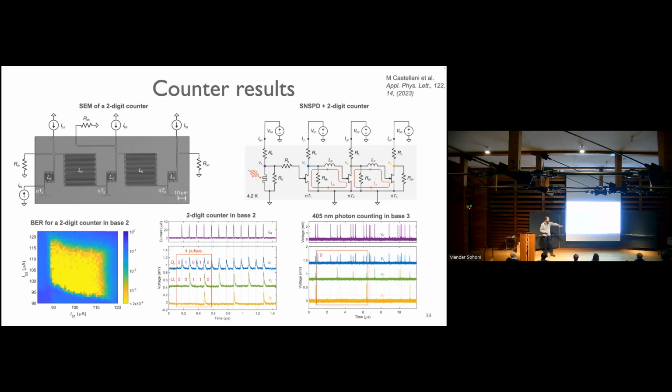It's like Olympic sprinter speeds. And that velocity is squared when you think about the kinetic energy. So the kinetic energy of the charge carriers in these devices is absolutely enormous. It dominates, through what's called kinetic inductance, by a factor of 1,000 over any magnetic effect.